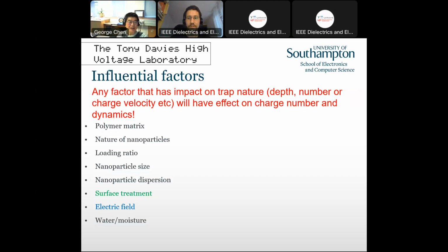But in reality, that may not be true. You may see some agglomeration of the nanoparticles, and that could lead to significant local stress enhancement. In some cases, when we do the measurement, we experience breakdown. While we assume it's uniform, in reality it is not well dispersed. I think that's something always a concern for nanodielectrics. Okay, thank you very much.